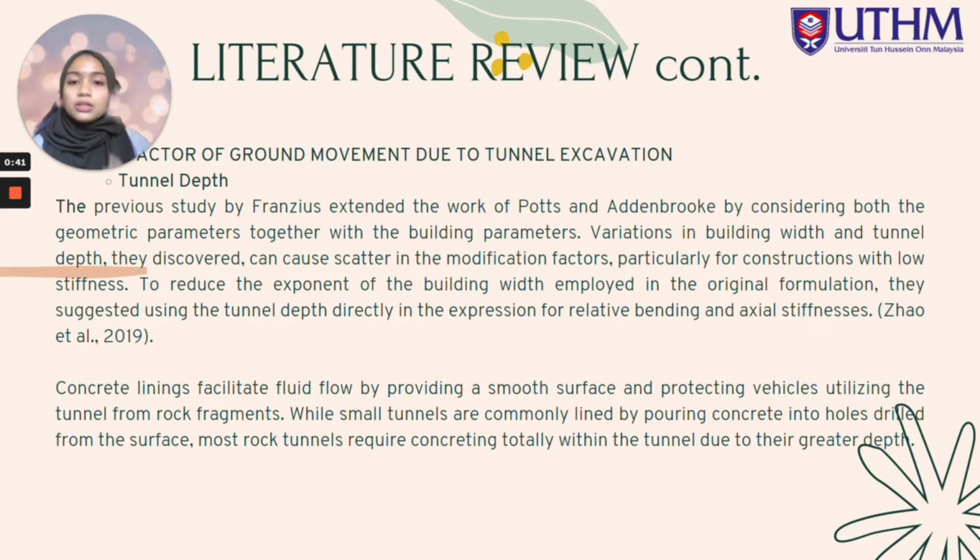To reduce the exponent of the building width employed in the original formulation, they suggest using tunnel depth directly in the expression for relative bending and axial stiffness.